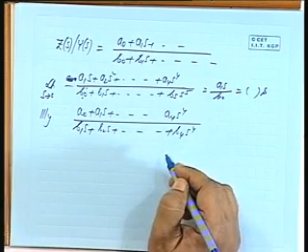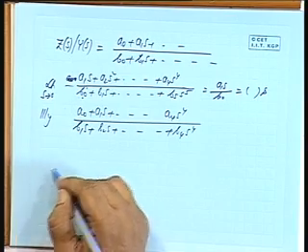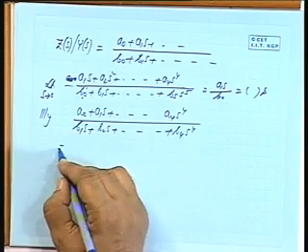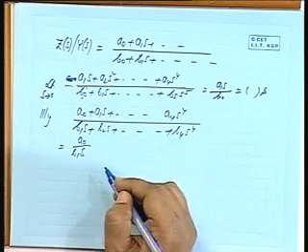Is it possible to have this term B0 absent? Once again you put S tending to 0, it will be tending to A0 by B1S, it will be tending towards a capacitive element. That is also possible. So, the last term either of the numerator or of the denominator may be present, may be absent.